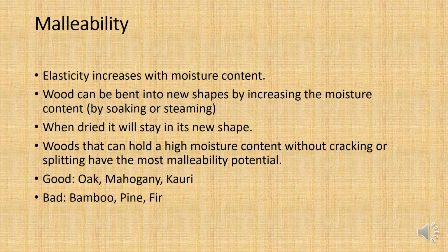So what sort of woods would you use for this? Well, it needs to be a wood that has the potential to have a very high moisture content. And I mean a moisture content that could be up to 200% or even higher. So literally two thirds of the weight of the wood is actually water inside it. And if it can hold a very high moisture content, you can bend it into a new shape.